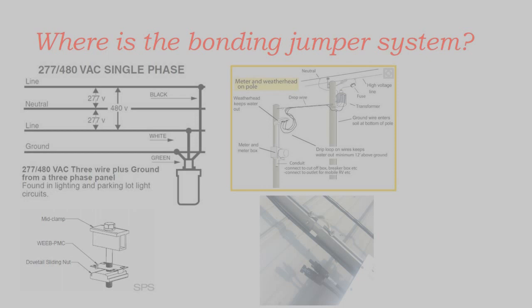But basically, when we're talking about solar power and on-site energy management systems, you need to ground all metal parts, and you'll make mistakes when metal parts that you think don't need to be grounded do actually need to be grounded. All your metal parts and your battery systems, etc., need to be grounded.